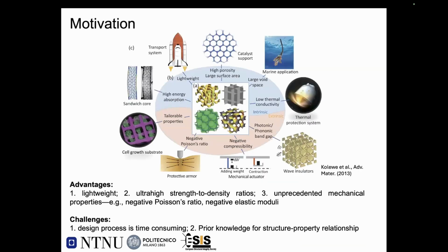Now, let me give you a brief introduction. The motivation of this study is the extraordinary performance of lattice materials, which have received high interest recently. The advantages of lattice materials are that they can be lightweight and have ultra high strength to density ratios, and scientists have already found they have unprecedented mechanical properties, for example, negative Poisson's ratio and negative elastic moduli.